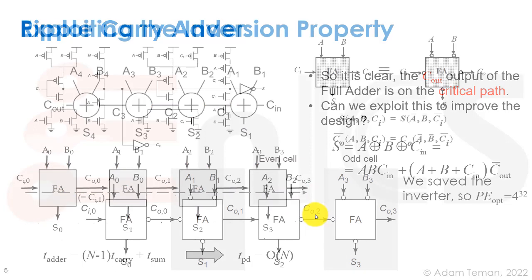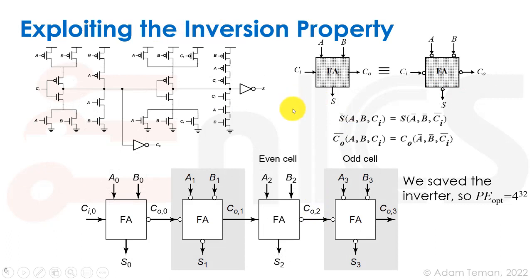But even before that, just taking a standard mirror adder, I wanted to discuss this because it's a pretty cool idea and I really like it a lot. If we redraw our full adder to benefit the carry versus the sum, we get this strange structure where we can also remove some transistors and arrive at this interesting thing, which isn't basic CMOS, because the pull-ups and the pull-downs are equivalent.